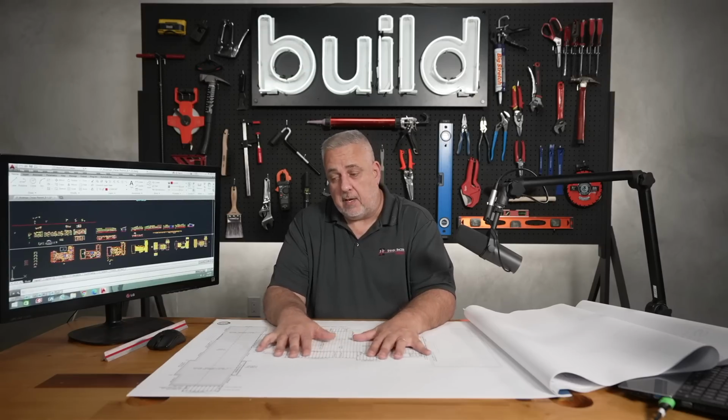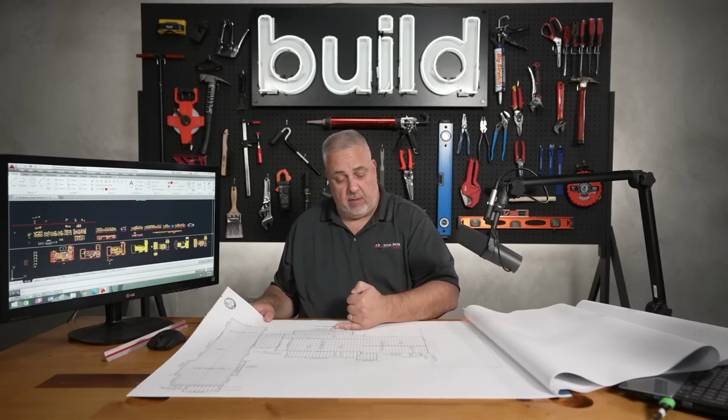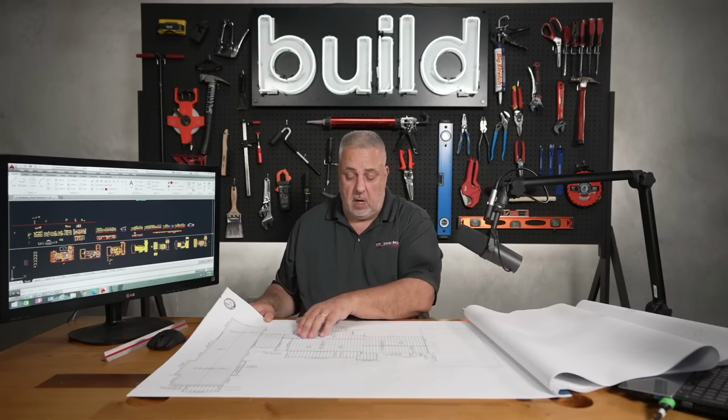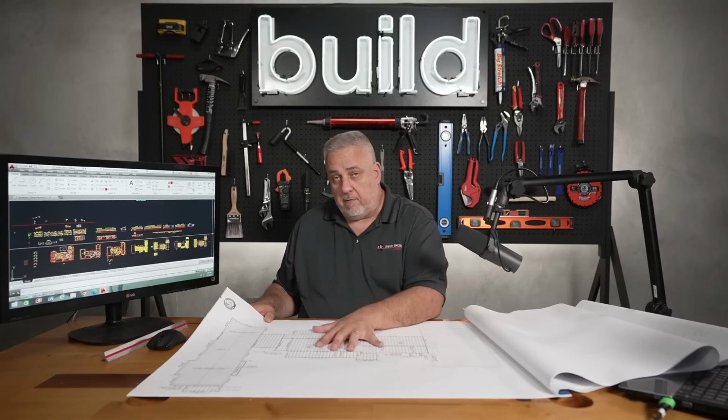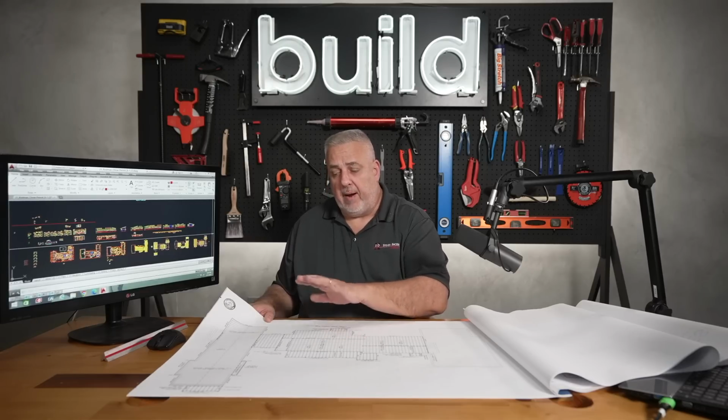And that's every detail. I can walk through and I can pull a dimension for everything from how the front stoop is dimensioned and how it's put together and what size ledger is hanging off the wall to what size these beams are, etc. I send all of this information. I put it together. I do an initial sizing on all the beams, and then I send it to my structural engineer.